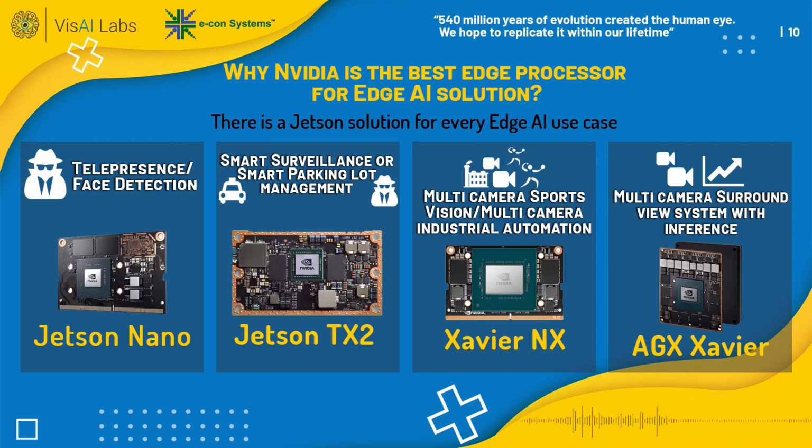But if it comes to smart surveillance or a smart parking lot, you may need to download a lot of data from the cloud, and you will have to compare it. In that case, you can go for TX2. When it comes to sports vision or a multi-camera system, you can choose Xavier NX. One of our customers has integrated up to 6 cameras to Xavier NX. And for a surround view system, for example fleet management, you can go for Xavier. So you can have all 6 cameras streaming at the same time, and also run the inference engine on top of it.